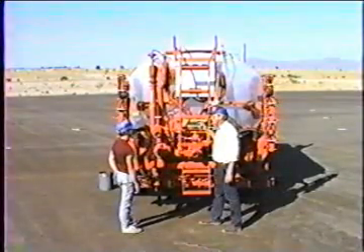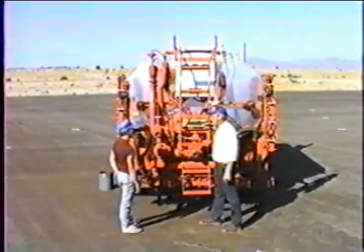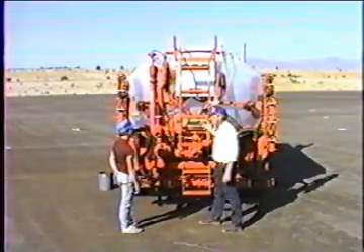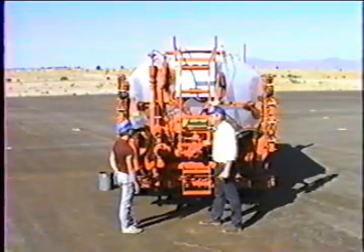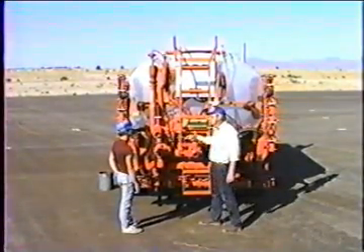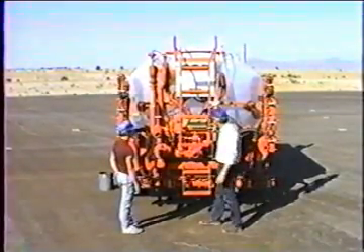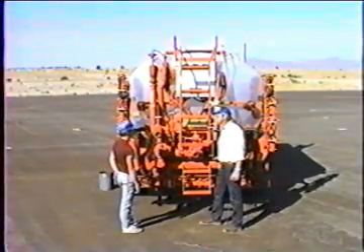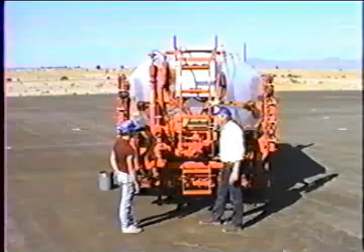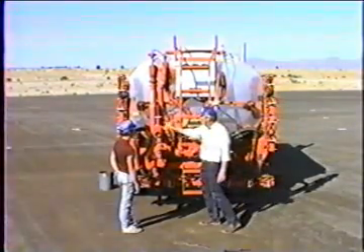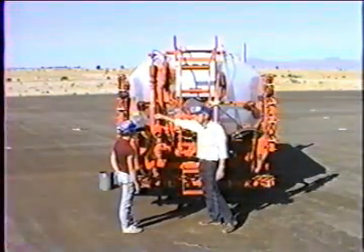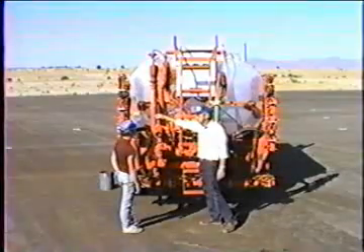As we get back in the cab of the truck, we're going to put the pump back into forward. On the computer, we're just going to tell it to circulate. The pump goes back into the forward direction. That valve's still open, this is still open, the tank valve is still open because we were in the load condition. The only valve we fooled with on the back of this truck to load it was this one, the load valve here.